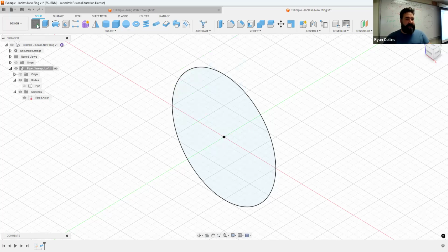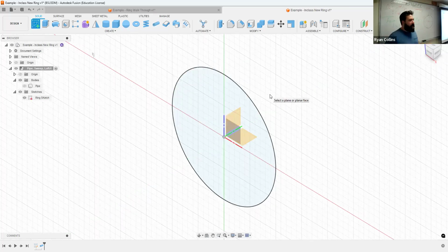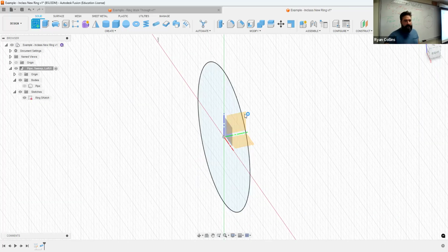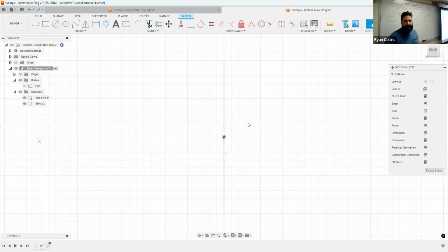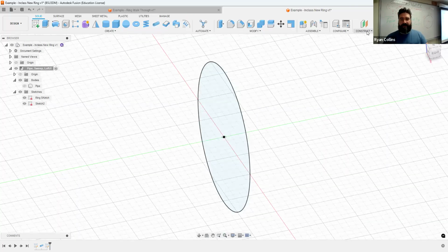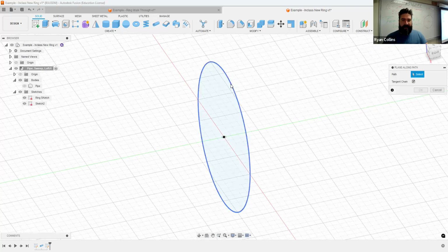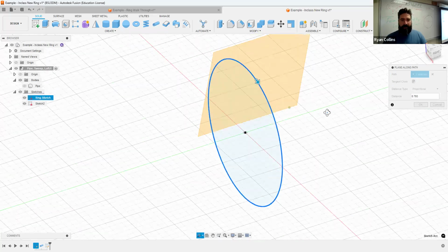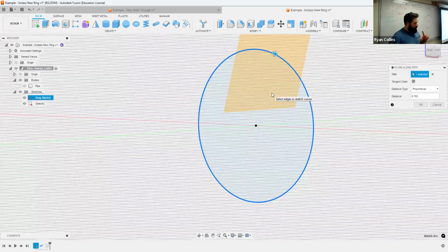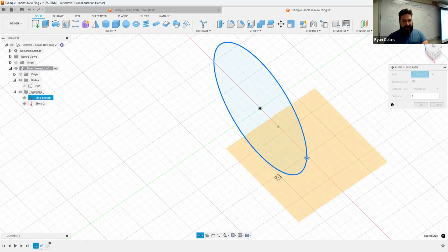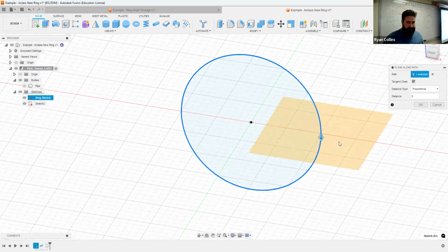So with this, you want to create a sketch. Now, this gets a little awkward because technically you'd want to make this perpendicular to the sketch, but then that line gets a little bit lost. It's kind of difficult to do. You can use this sketch, but just for reference, you can actually do a sketch on a path, and you can select that one and it'll create it basically anywhere you want. So if this was not a complete circle, if you wanted to make this anywhere along a path, you could do this. It makes it really easy.